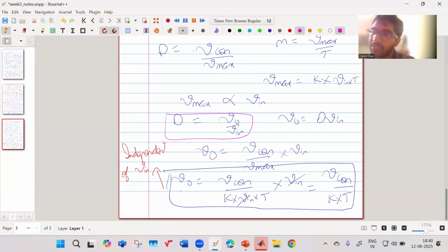And you should not make silly mistakes or blunders, right? That is there. So feed forward gives you a kind of advantage. It gives you that extra information, which gives you an edge, which improves you. Okay. So that is the thing about feed forward control. But feed forward control in this explanation which I've derived, and in other cases also, is very idealistic. Practically, it will not completely eliminate the error, it will not give you completely accurate regulation.